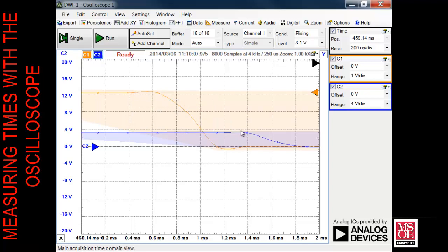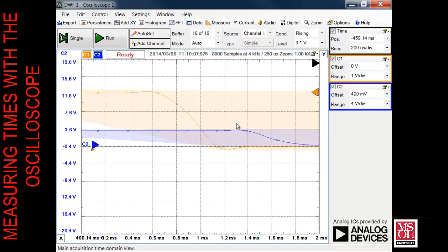If I go then down to here where we start seeing the change on the LED, 458.746, we can do the math between those two, and we can see that we've got 1.006 milliseconds distance or latency between when the push button is actually pressed, which is this upper line, and when the LED starts to change.